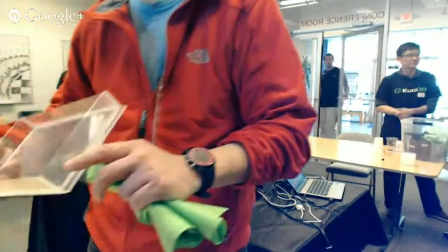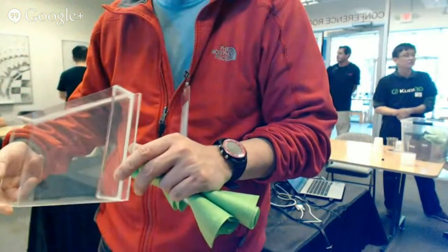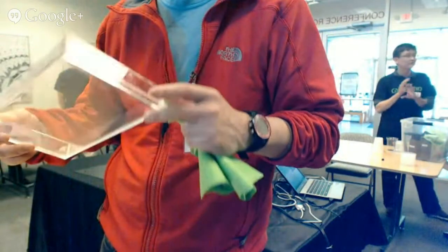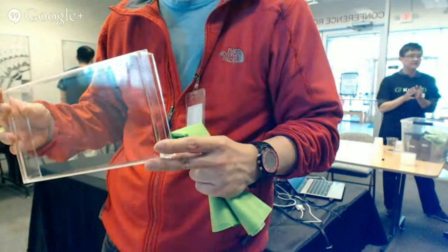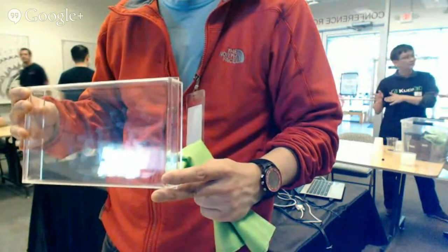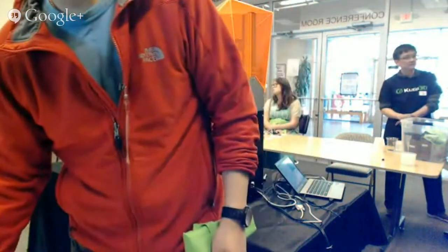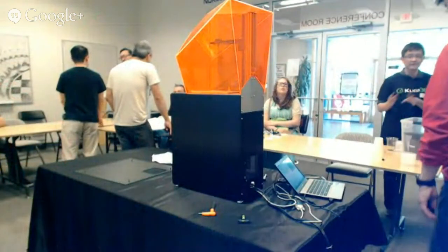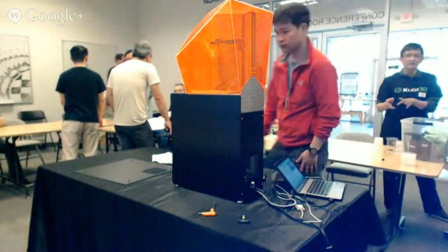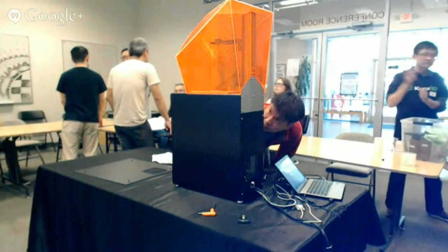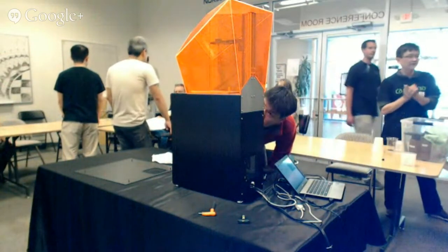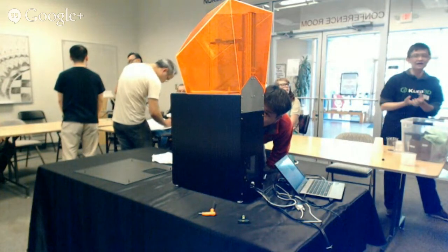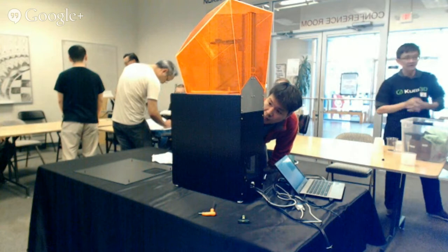The purpose is to make it stronger, and aluminum filled epoxy is commonly used to make prototype injection molds. So for instance, if I wanted to produce an injection mold in a non-computerized way, I could make a silicone mold of a part and then hand carve the features into the silicone, and then make another silicone mold of the silicone mold pads, and then fill it with epoxy.